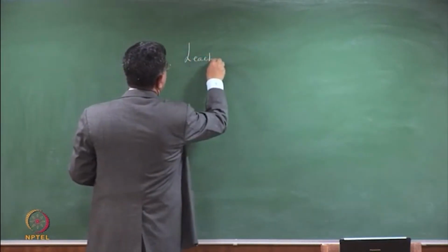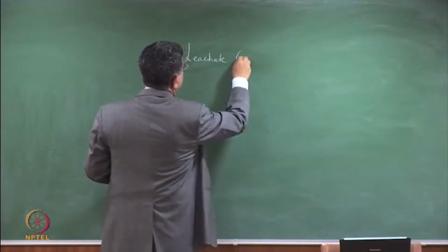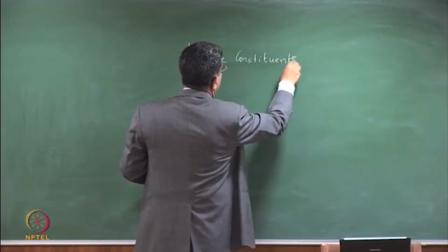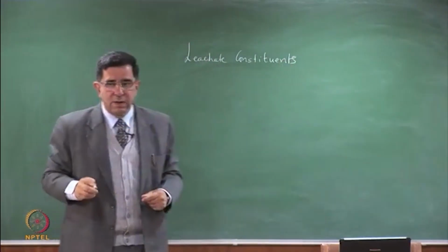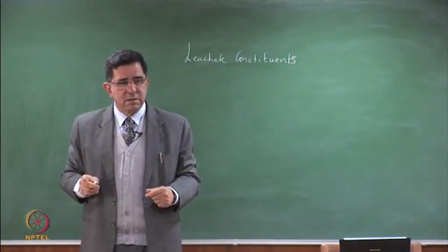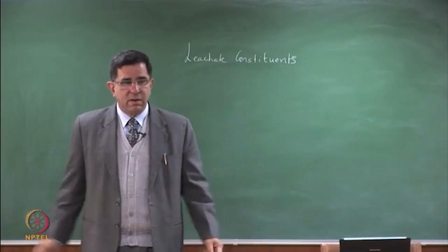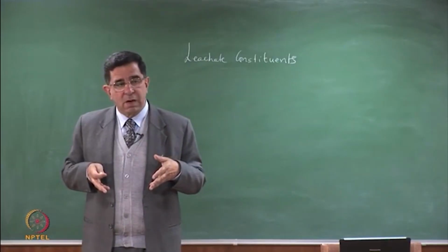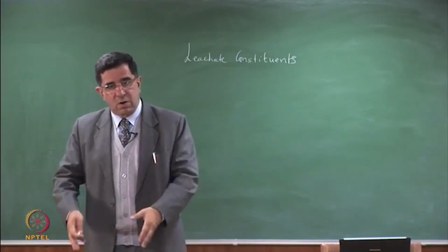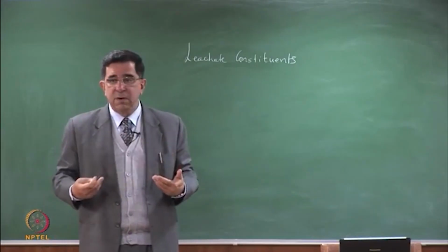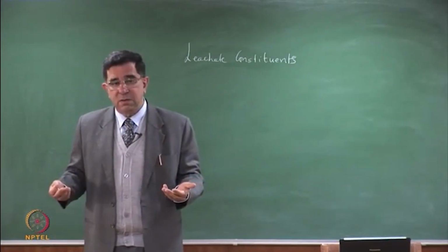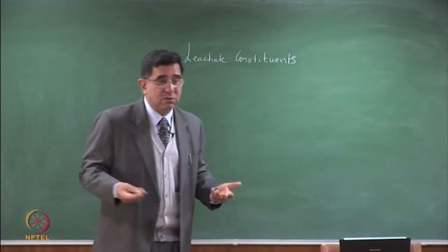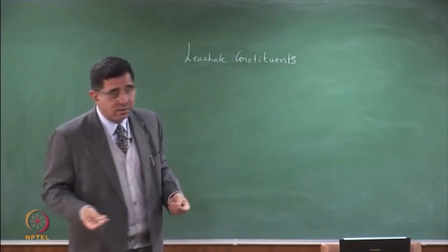So, I have leachate constituents. Should I compare them with drinking water standards? Why not? Eventually, if the liquid is going from the waste mass into the ground, into a groundwater which I am using for drinking water purposes, then should I compare it with drinking water standards? Well, one of the set of standards which are available in the codes is the drinking water standards.